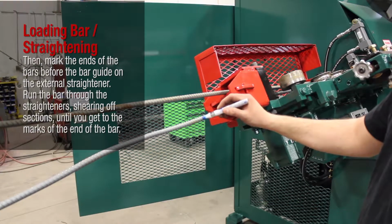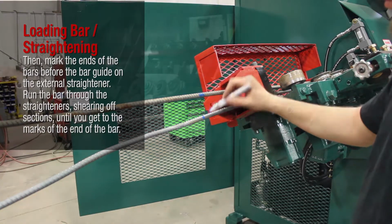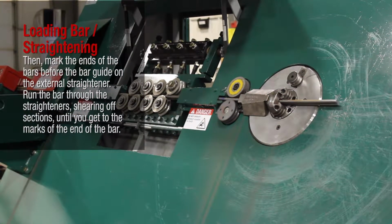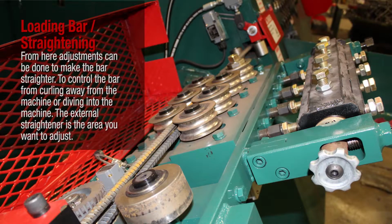Then, mark the ends of the bars before the bar guide on the external straightener. Run the bar through the straighteners, shearing off sections until you get to the marks at the end of the bar. From here, adjustments can be done to make the bar straighter. To control the bar from curling away from the machine or diving into the machine, the external straightener is the area you want to adjust.